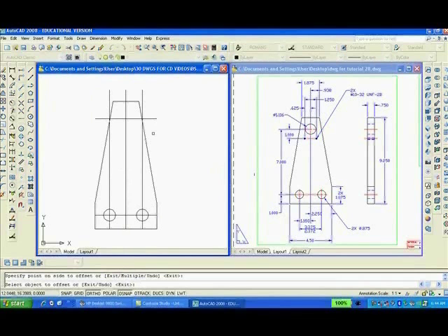And we can type C, enter. I'm still on offset, so escape, C, enter, pick this intersection, D, enter, 1.116, enter. Now I can erase the unnecessary lines.